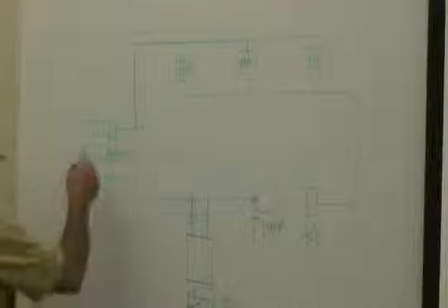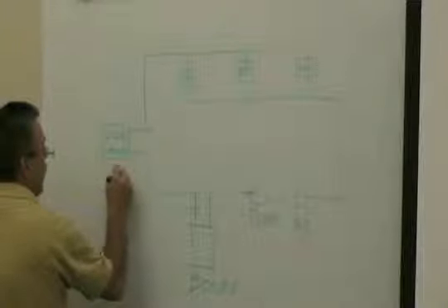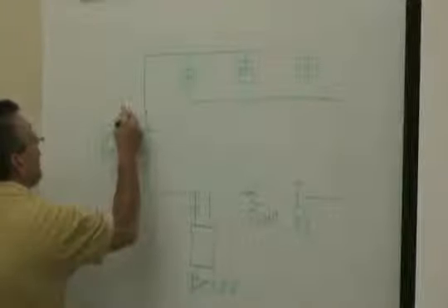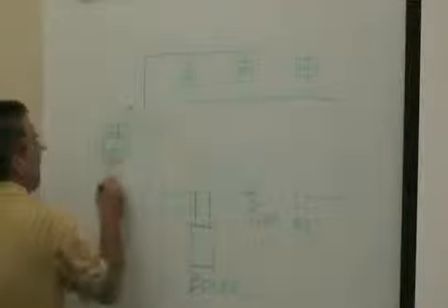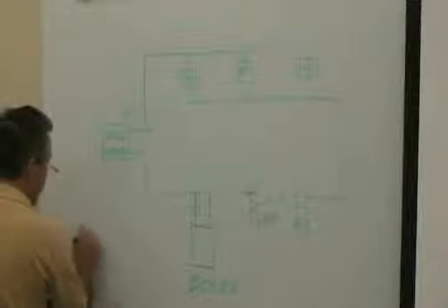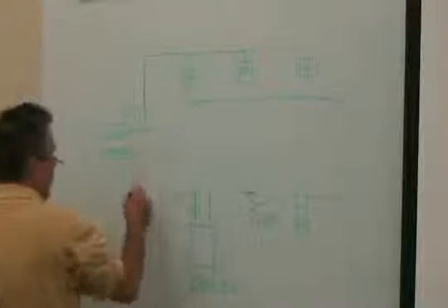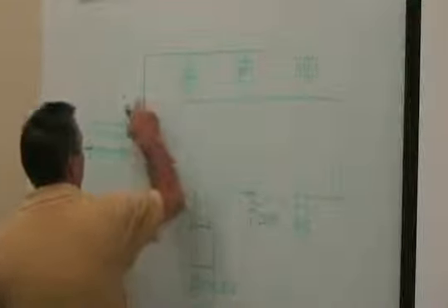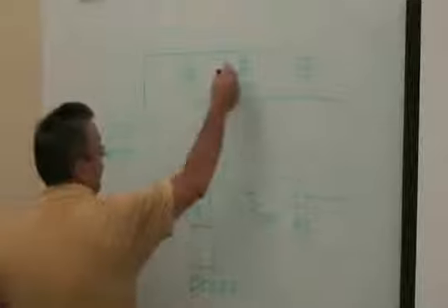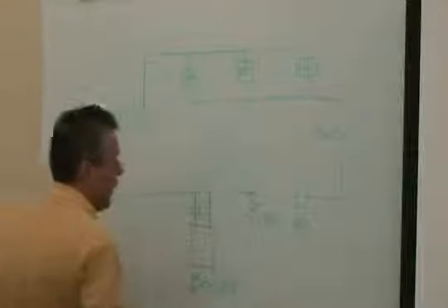Okay, normal operating, this operates similar to a cooling tower, so I can probably produce something like 90-degree water here with 100-degree water coming in. So my range is going to be 100 to 90 degrees during the cooling season. So I'll send out 90 degrees to all the heat pumps, and it's coming back at about 100 degrees.